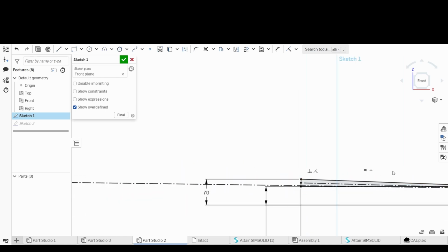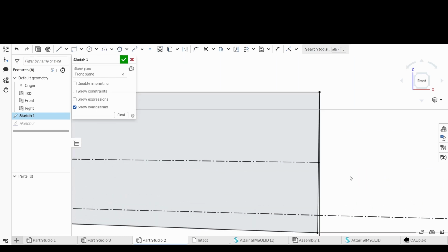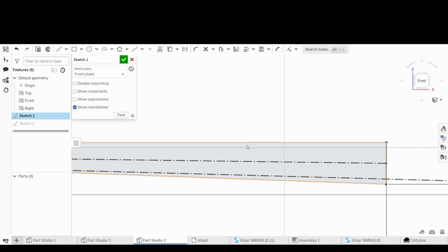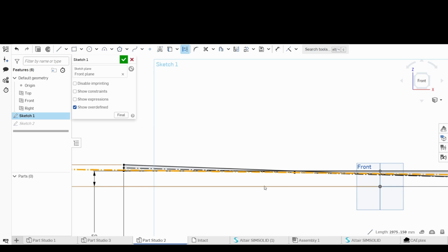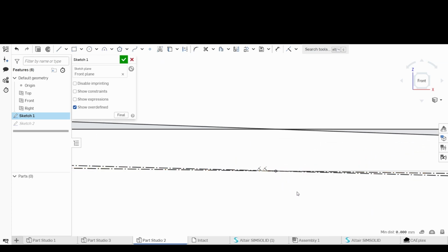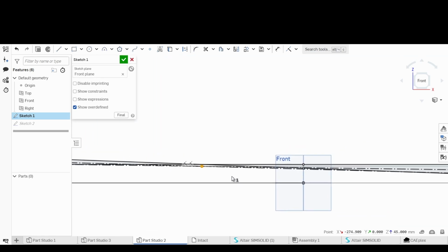So you draw one on one side, and then you do the same thing on the other side. Again, a point from the static ride height to the dynamic line at the midpoint perpendicular to that. And where those two lines cross, right here, that's the point that the chassis is actually rolling about.